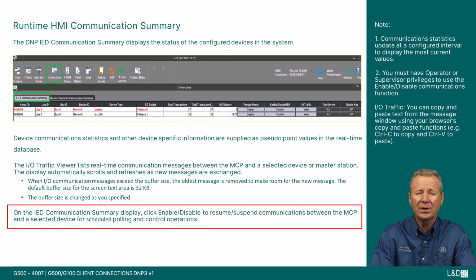On the IED communication summary page, click Enable/Disable to resume or suspend communications between the MCP and selected device for scheduled polling and control operations.